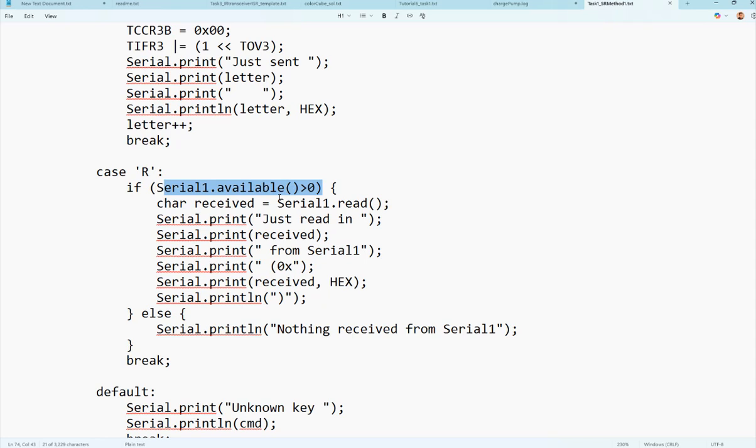And so the interrupt will be triggered when everything is received. Which means when it pulls it down, because hardware physically the decoder's output is shorted to RX1. So when the data comes in, it starts receiving, starting from the starting bit being put down, then pumping every single bit in, boom, boom, boom, boom, coming into the RX module, okay? Once all the 8 bits are received, they will be stored in the buffer in the RX module, and it's going to trigger that UART receiving interrupt, and so you can read from that.